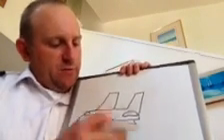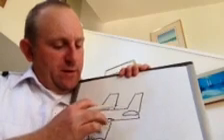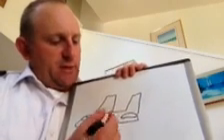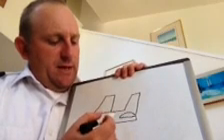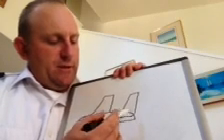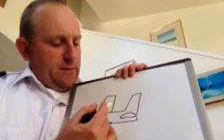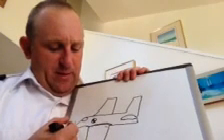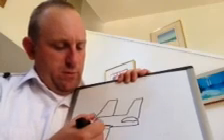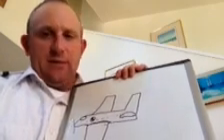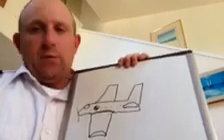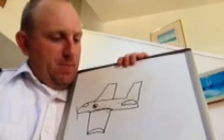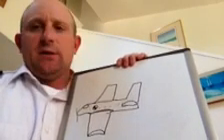So, the different types of tails that we have. We've got a conventional tail as illustrated right here, and this conventional tail has a good advantage in that it takes any kind of airflow, say we have a propeller, any kind of induced airflow, and takes that into account, because with our lift equation, we'll take note that velocity has a lot to do with how much lift is generated.